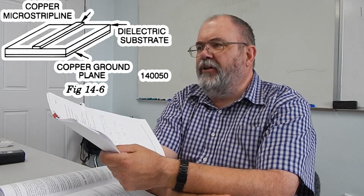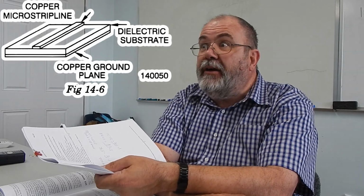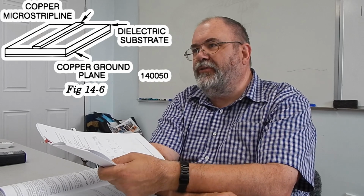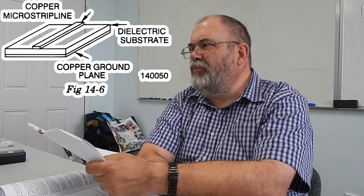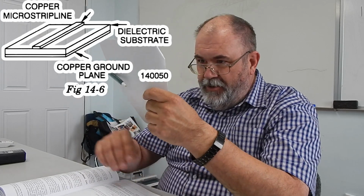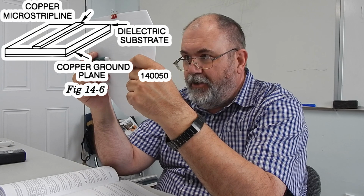Microstrip line sucks in a lot of ways, because it's only a single leg transmission line. It's not really balanced or unbalanced. It has virtually no shielding because it's out in the open. But hey, if it's an antenna radiating, well, you don't want shielding. But if you're coupling an RF stage in a device to another RF stage, microstrip lines are almost never used. They actually use little tiny pieces of coax cable jumpering inside from one stage to another. You could use microstrip line, but because of no shielding, it's not ideal. Okay. What is a printed circuit transmission line called? Microstrip line. Compared with coax cable, microstrip line has poor shielding.